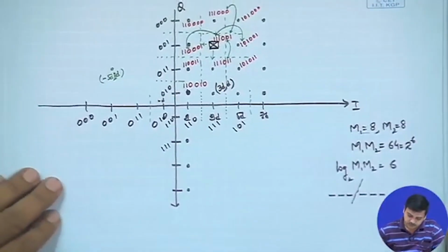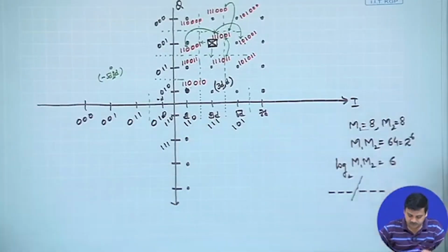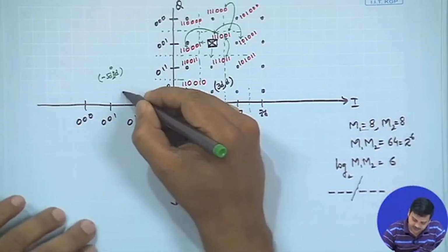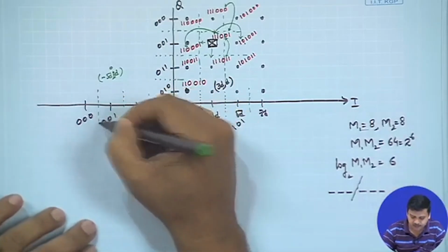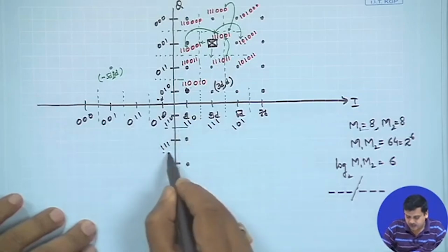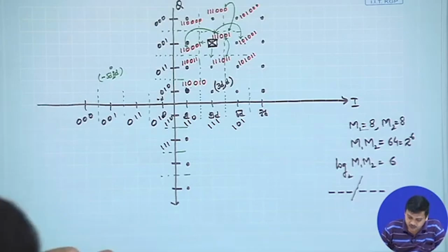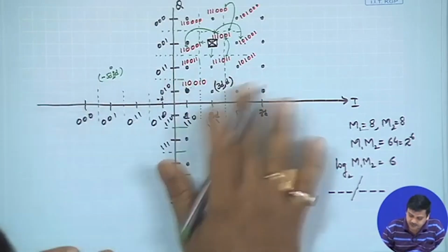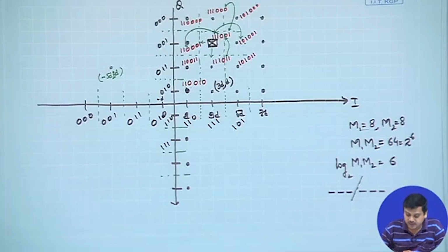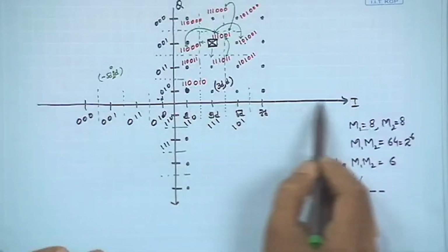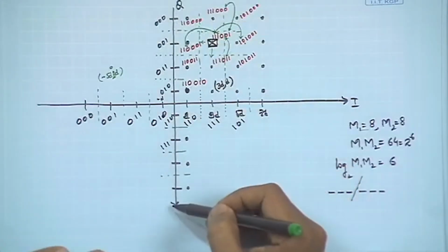You have your decision boundaries which are clearly symmetrical, and this of course appears for the case of memoryless modulation, right, and by symbol detection. If you are doing this, and in this pattern, as I have already mentioned, you can use a single PAM lookup table for generation, and you could use a symbol decision threshold for detection as well, because you can clearly see whatever we have in the I axis, you could use a similar thing on the Q axis.